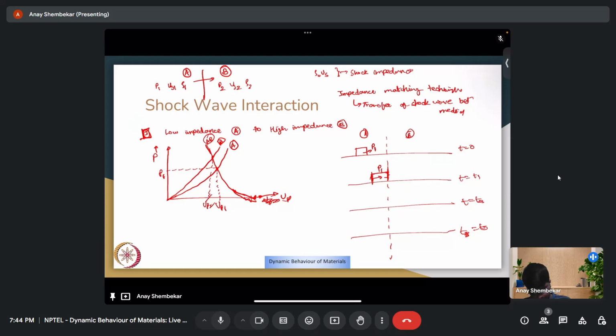It's also seen from the pressure and particle velocity plot. This is P2, it's P1. Then P1 and P2 will interact again, and after a relatively larger amount of time, you'll end up having a reflection with pressure differential P2 minus P1.